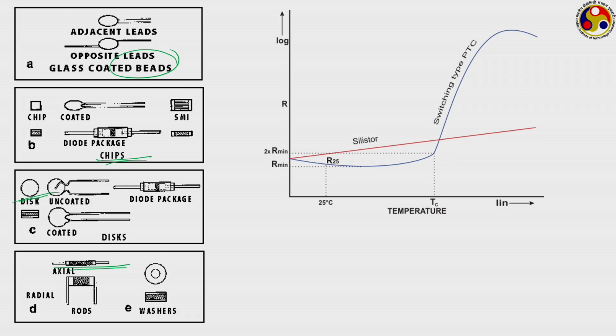Just check, initially for lower temperatures it actually has a quite moderate negative temperature coefficient, but beyond a limit, when it reaches the minimum resistance, it keeps on increasing, and beyond a certain threshold or critical temperature there is a rapid increase in the corresponding resistance value. For this purpose, often these PTCs, PTC referring to positive temperature coefficient based materials or materials having positive temperature coefficient.